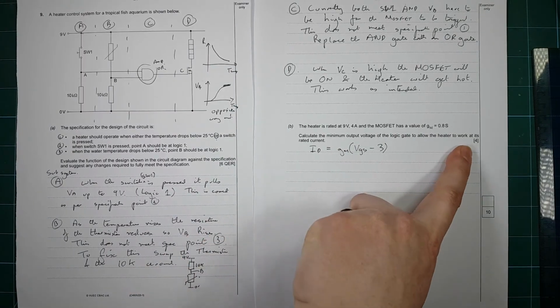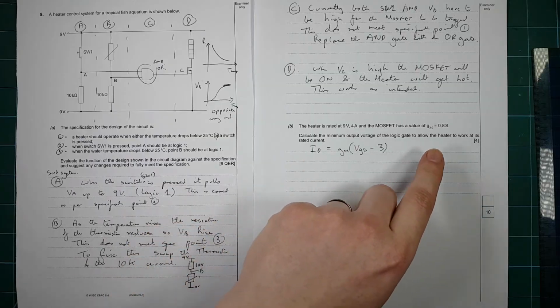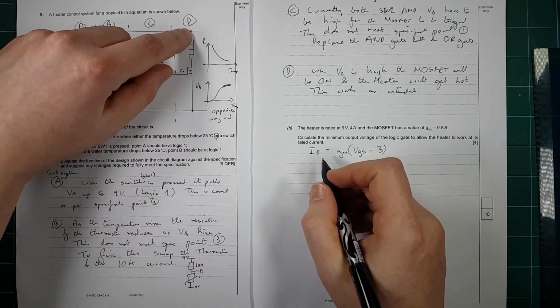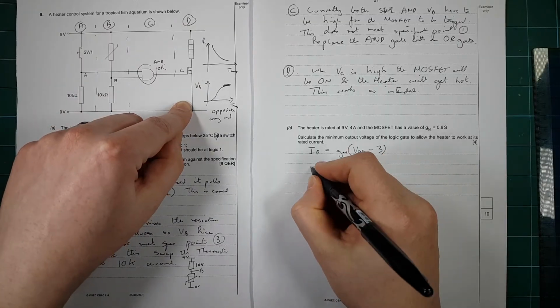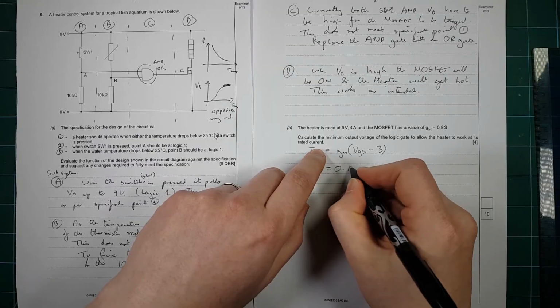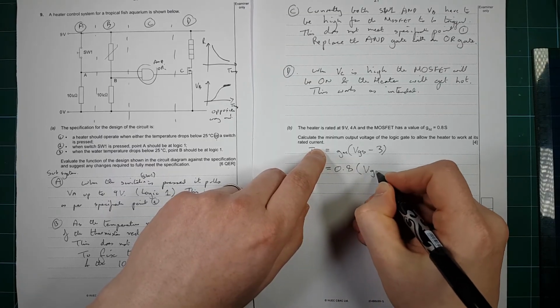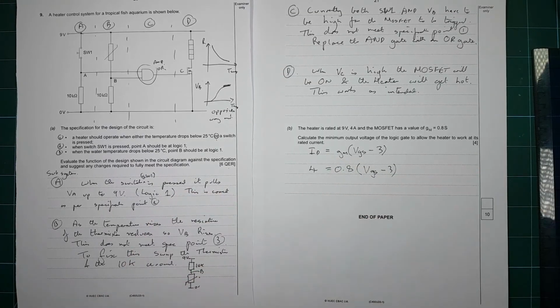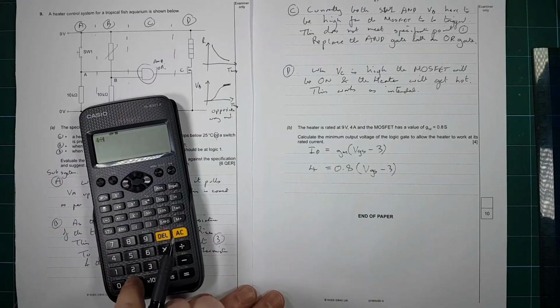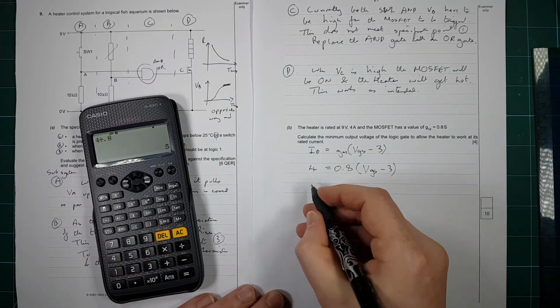So let's just shove the values in straight away. We want the current flowing down here to be 4 amps. So we put 4 is equal to GM, which is 0.8, times VGS, which is what we're trying to find, minus 3. It's much easier to just shove the numbers in than to rearrange the equation first. 4 divided by 0.8 is 5.